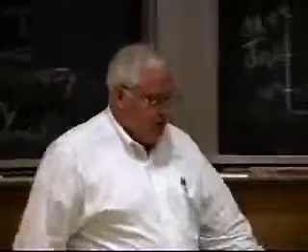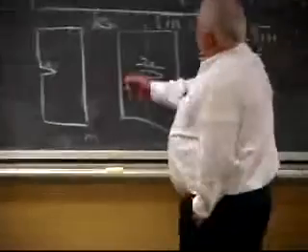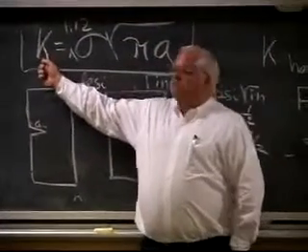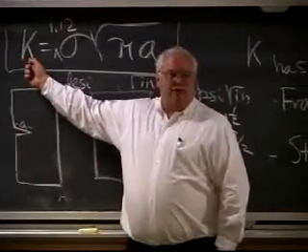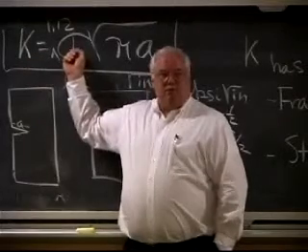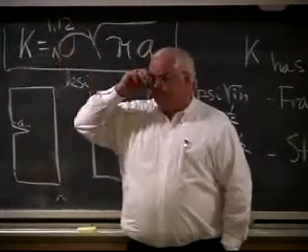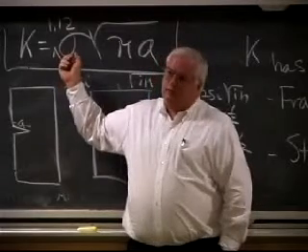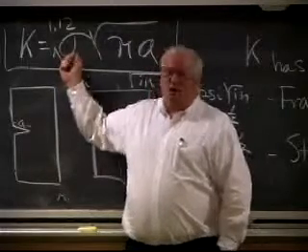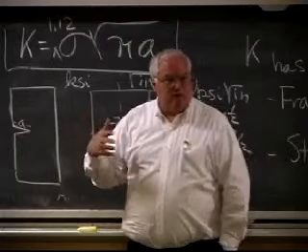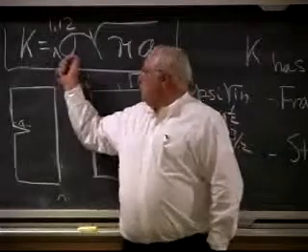Let's take an aircraft landing gear that I make out of a super duper steel, and it's got a fracture toughness of 70, let's say 75, and sigma has a yield strength of, let's say, 300, but I'm not going to operate more than about half of that because I don't want to get any high cycle fatigue or low cycle fatigue going on.